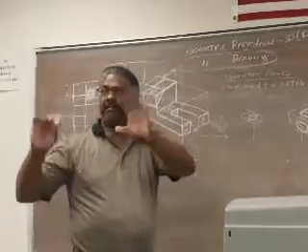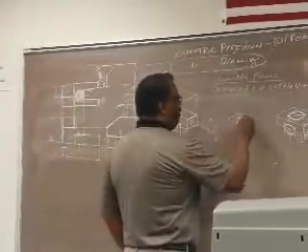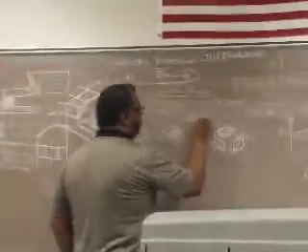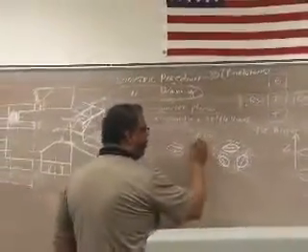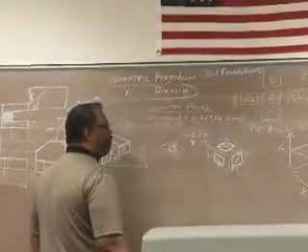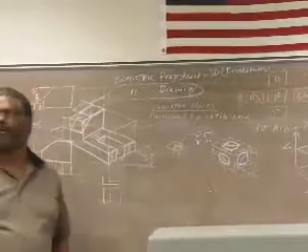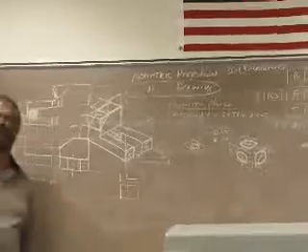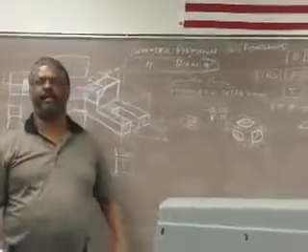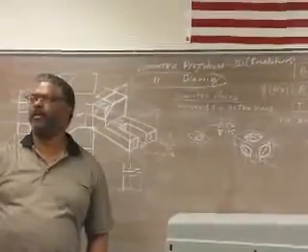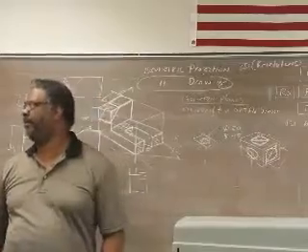But if it had the dimensions on it and went through the part, it would just have a size. If it didn't go through the part, it should give you the depth of the hole. So anytime we see just a circle marked like that with a center mark, we should assume it goes all the way through. Correct. If it's not a through hole, then it should show you a depth. So all holes are assumed to go through unless a depth symbol is given to indicate the depth of the hole.